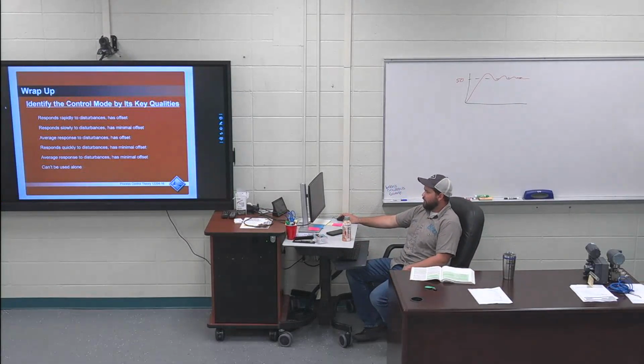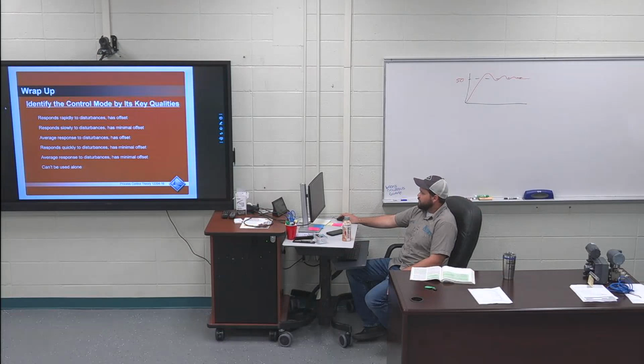Responds rapidly to disturbances, has no offset. What type of control is that? What type of control takes care of offset? You have proportional, integral, and derivative. You can combine them any way, except for integral and derivative together, or derivative by itself.